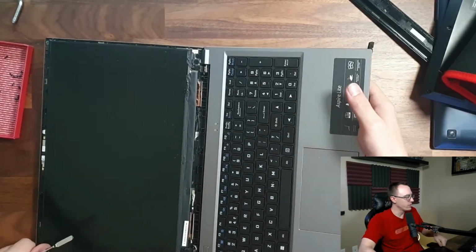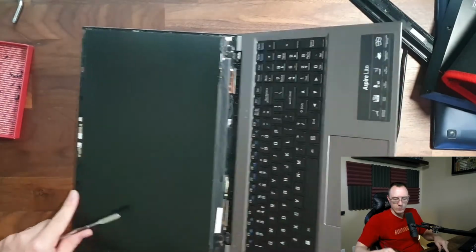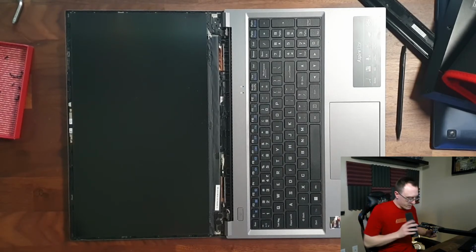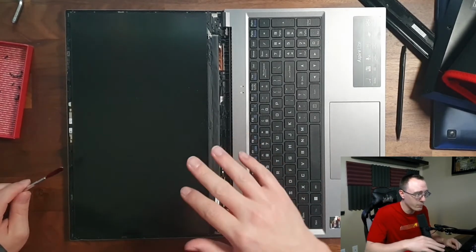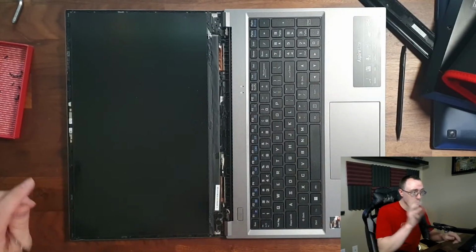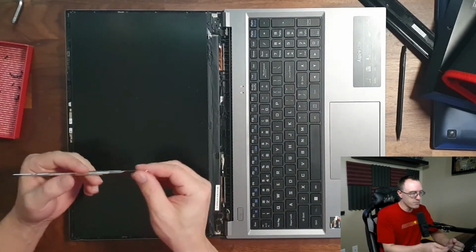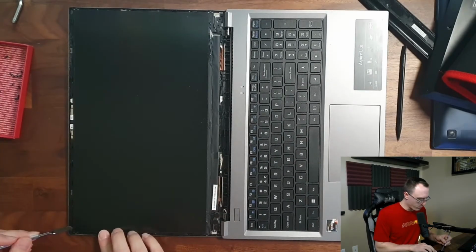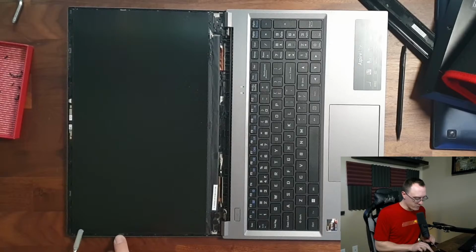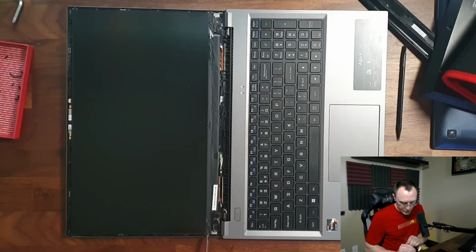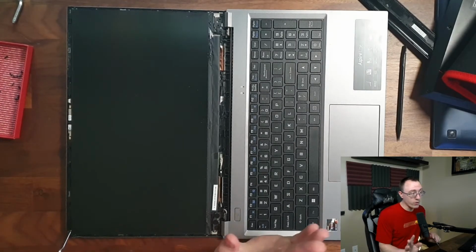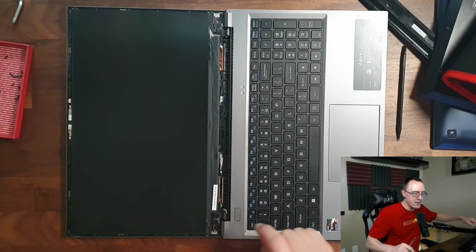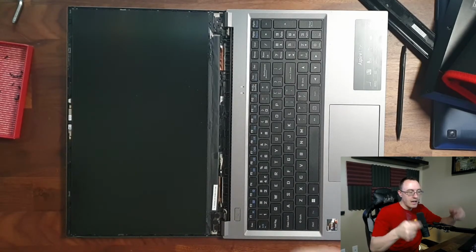Try to make some room here. Okay, because I would like to also see myself, but I want to make sure that when I'm looking, I'm not over the actual screen, right? First time doing it in this new setup. So to source the screen, I'm going to take the metal spudger here, which I wouldn't recommend doing, because you will break it. But the tape usually is something that runs along down the sides here, and there's usually a little pull tab. And those pull tabs rarely work anyway, but they allow you to get just enough to pull it out, and like those 3M strips, it'll expand, it'll stretch and loosen the adhesive, and then it will allow the screen to come out